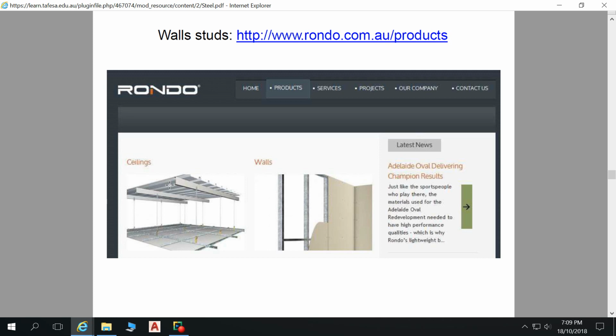Basically they just provide a fixing point for our hangers. Those hangers have to fix to something, so an easy way of doing it is with a C channel. Then those hangers are connected to these ceiling sections that are installed in a grid fashion.